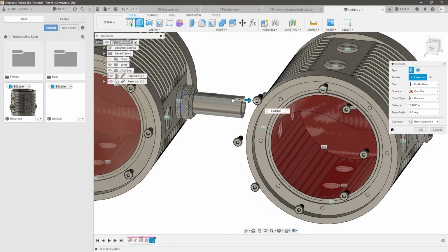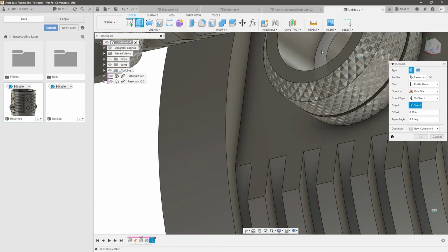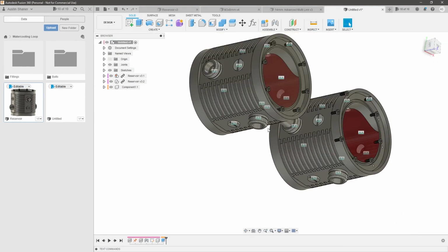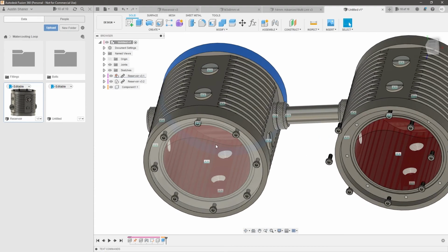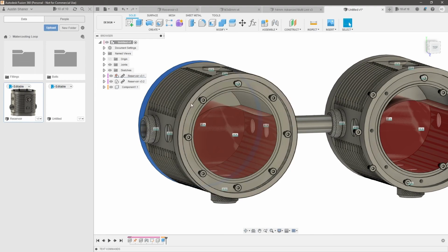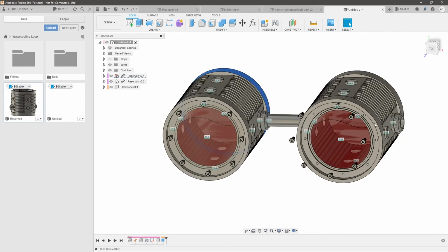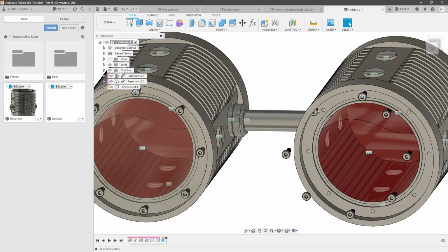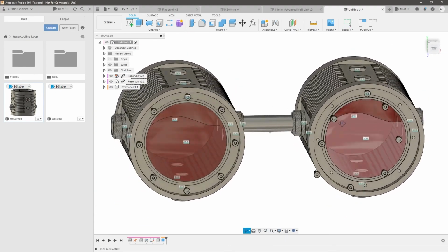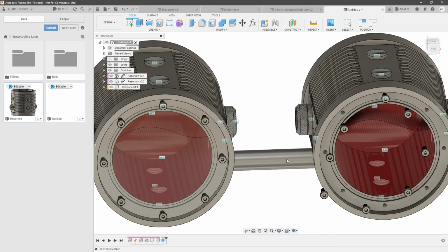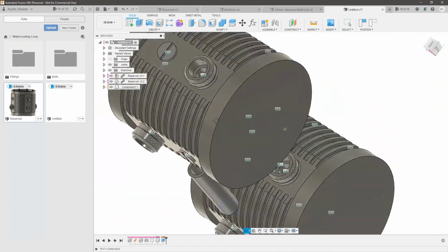And we want to now reference the inside face of this one. So we will go to object here. So you'll notice now we are actually back to top down. So we built the body and this glass as top down. And then we added in the bolt and the fittings as bottom up by having them as separate part files. And then we added in this reservoir. It looks like these bolts got a little messed up, so I might have to fix that. But we added these back in as a bottom up, as a subassembly. And now we've created a pipe that is referencing in the context of this assembly. So this is also top down.